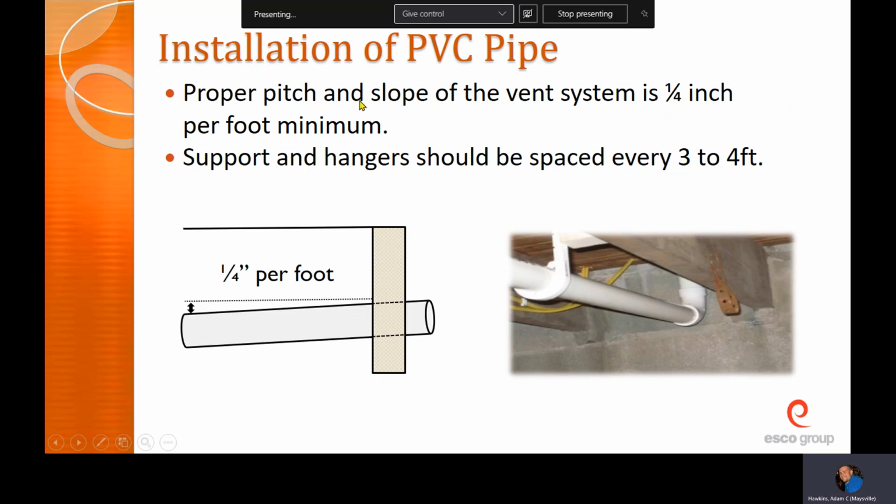As we mentioned before, part of the purpose of this pipe is not only to get rid of the gas, but to take care of the water. Because this is running at such low combustion temps, it's really close to the condensing point of that water. So if it cools down even a little bit, you're going to get more. Let's say this is running through a basement or a crawl space. As soon as it leaves the furnace, that pipe is colder than it was in the furnace, and so you're going to lose heat to the surrounding air. It's not insulated or anything like that. It's not supposed to be. So you're going to start to condense. You're going to get water.